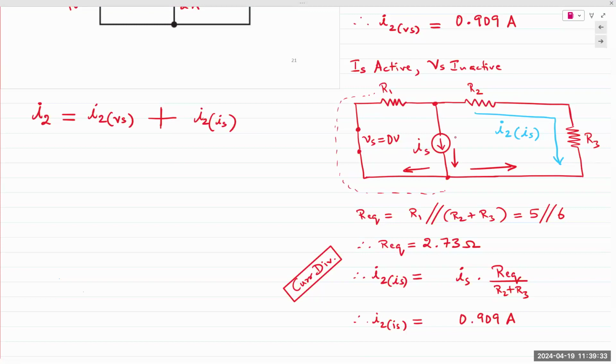If a current direction is indicated in the problem statement, all it means is that you have a meter and you're measuring the voltage or current according to the indicated polarity or the current direction. In this case, the indicated direction is coming down from the top. Current flows from high to low, plus to minus. A multimeter or a digital current meter or a voltmeter also has 2 terminals, plus and minus. The tail end of the arrow is where the plus of the meter would be connected. And the arrow head is where the negative terminal would be connected. Current going from plus to minus.